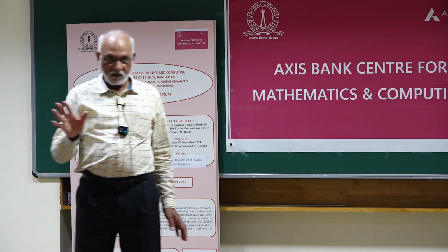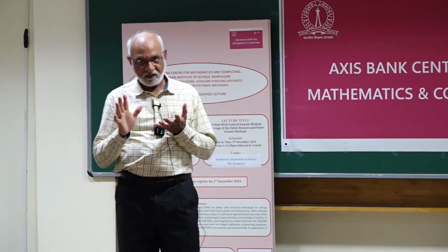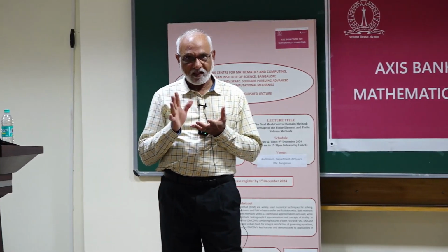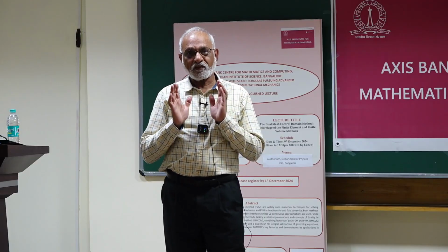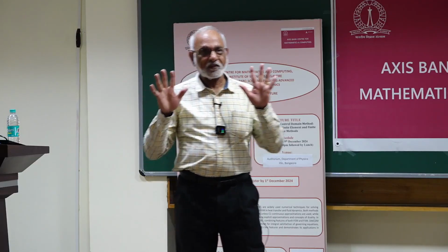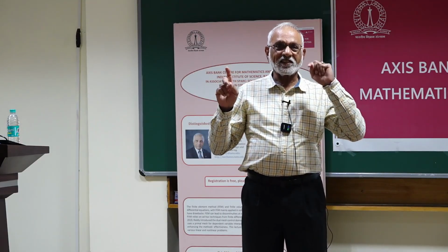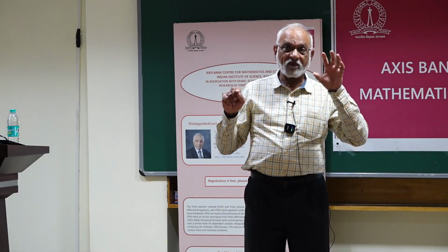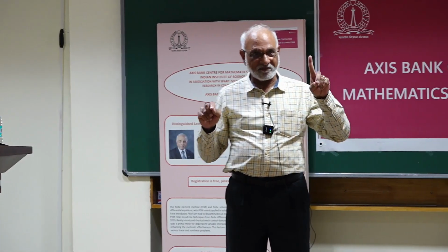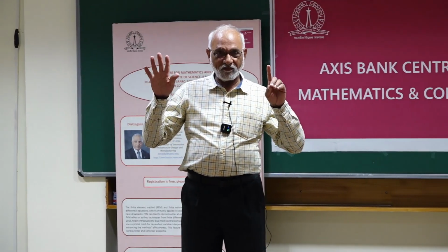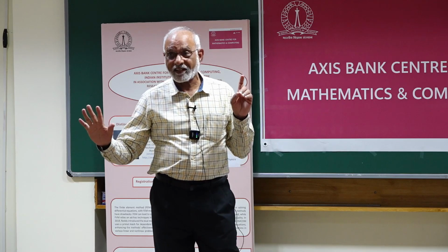Yeah. So, this again begs for me to explain the physics, because physics is where we have to pay attention. Computations follow it. So you have to write where the difference is between the two field problems, fluid mechanics and solids. It is in the constitutive equations. Because fluid mechanics relates the stress to velocity gradient, whereas solid mechanics relates it to displacement gradient.